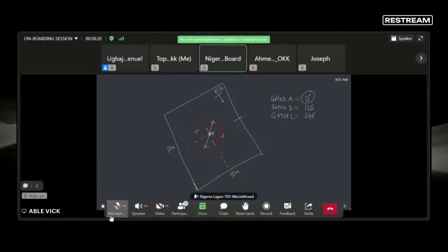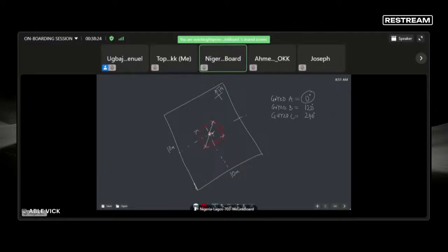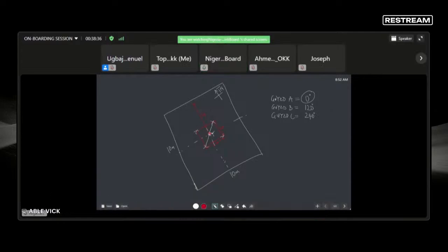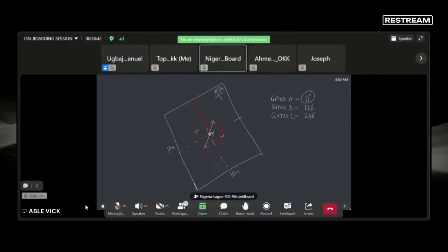You measure 5 meters from the middle of your tower towards the north. And this is our measurement. This is our 5 meters. From here to here now is 5 meters. Towards the north, if you check it, you can see it's still parallel to the north. That is your 5 meters. So at that 5 meter point, that's the middle of your guide wire base plate.